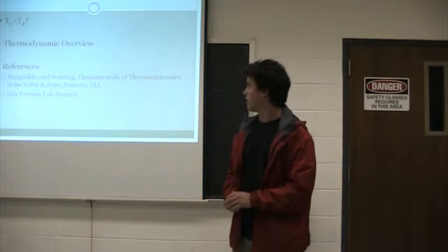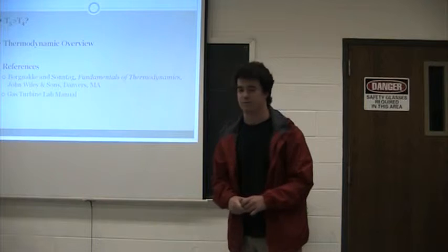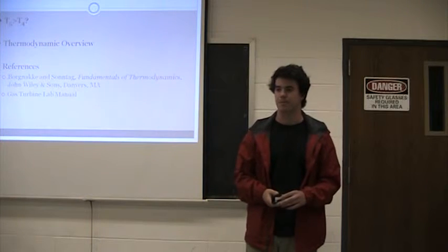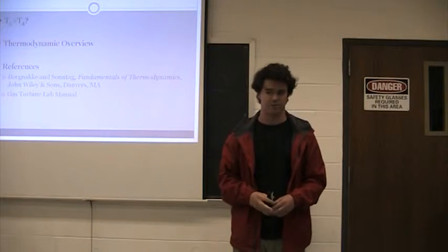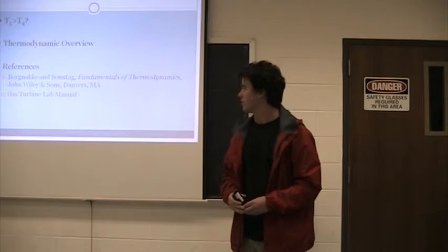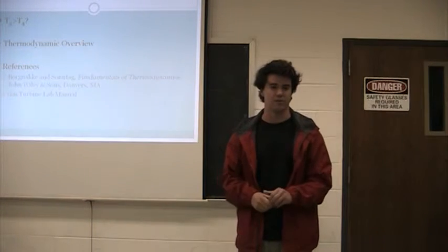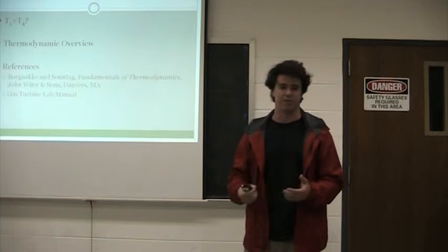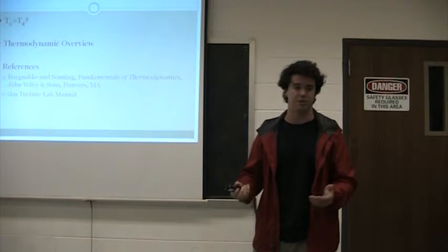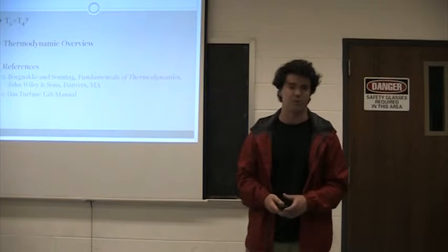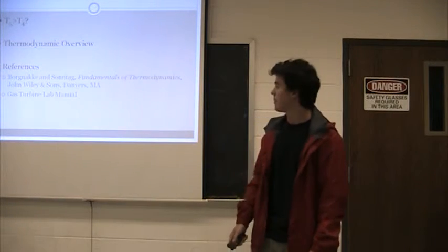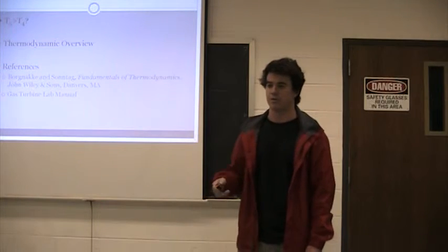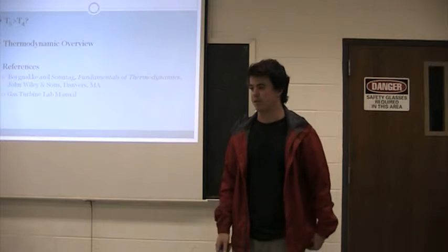Final conclusion: my experiment temperature wasn't matching the factory results, which I found odd. I chalked this up to the fact that the smaller the nozzle we're working with, the temperature being expelled is a high pressure situation and a high speed, and that could possibly be why we have a higher temperature there. We looked at the Brayton cycle, we looked at calculations we used back in thermo that I hadn't used in forever.